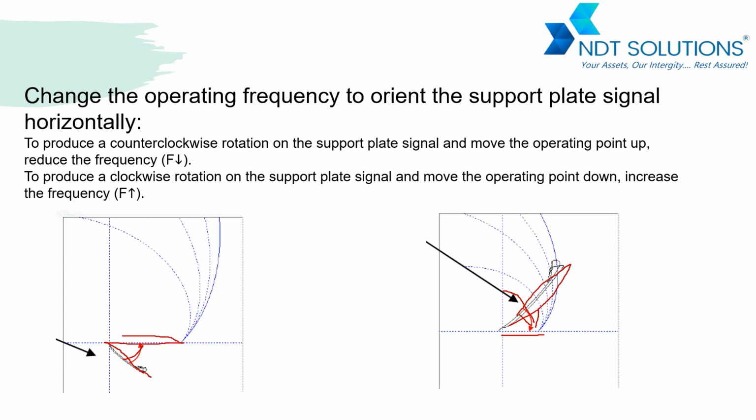We cannot bring all the baffle plates to the zero position. But we can try to bring them into the realignment zone. Realignment zone means that the variation in any of the bundles should be 30 to 45 degrees. If it is there, then our frequency is okay, and if it is not there, we need to do this practice.